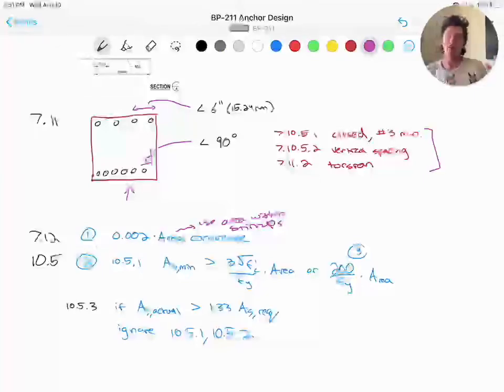Because if we use the entire gross area of the concrete beam, this wouldn't pass, but we are only needing this smaller section to resist shear and flexure, so as the designer, I've chosen to validate this by saying because we are well above our capacity and the beam is getting cast into a greater structure, we're going to use this smaller area. But ultimately this assumption can be left up to your design engineer in charge.